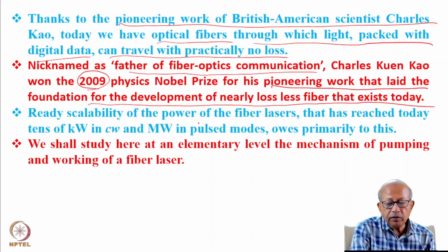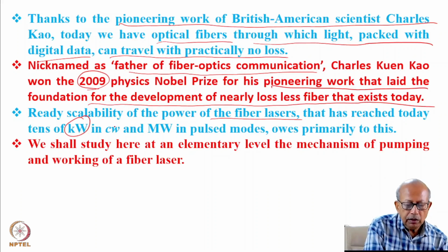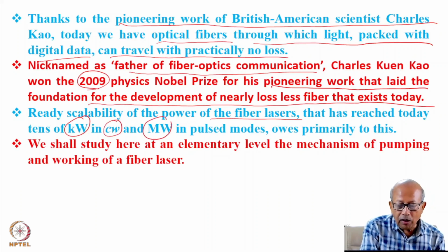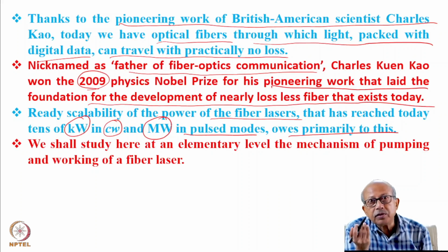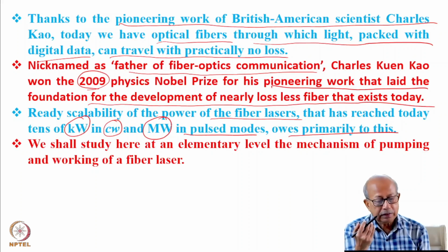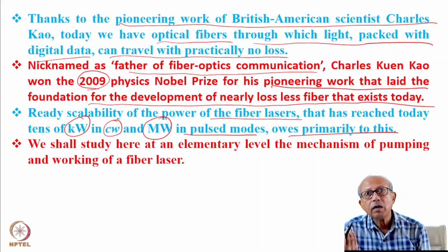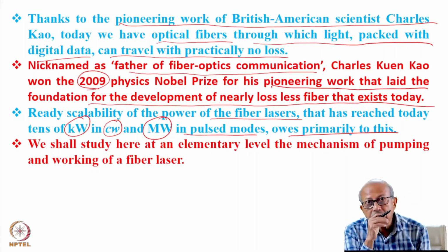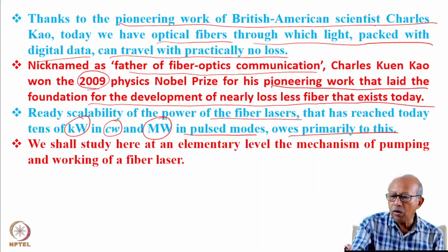And the ready scalability of the power of the fiber laser, which has reached today tens of kilowatts in CW operation and megawatts in pulsed mode, owes primarily to this, because this fiber hardly absorbs any light. Therefore, the power of the fiber laser can be greatly enhanced as it suffers hardly any absorption of the incident light. The credit, of course, goes to Charles Kao.